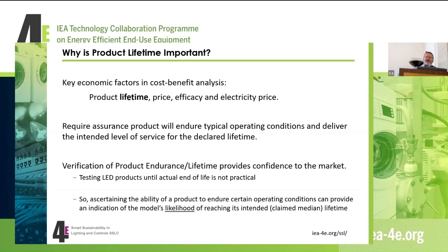But unfortunately, with the extended lifetimes that we have for these products now, we can't test till the end of life for these products. As you can appreciate, we're talking about products that have lifetimes of 15,000, 25,000, even for luminaires and so on, 75,000 hours or more. And if you operate continuously, you get just over 8,000 hours in 1 year. So to test something that's got even a 15,000 hour lifetime, we have to test it for 2 years continuously just to get the results for a product before it can go onto the market.